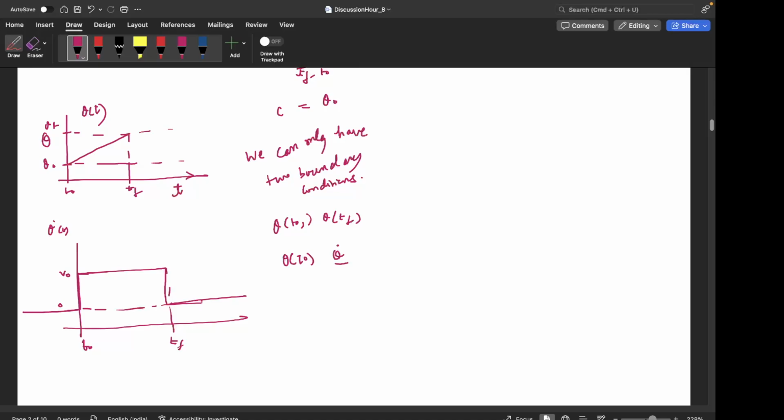If we are going very gradually, they would work fine, but generally they are avoided because at the start and the end point they lead to a jerky motion. If the velocity is high enough, the end effector or the manipulator would suddenly get a steep velocity, then move with that velocity, and then come to a rest abruptly. So that is the linear profile.